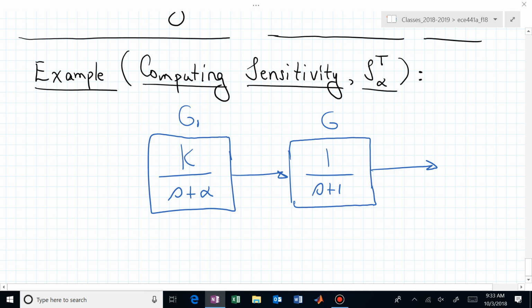It's stable, isn't it? It's in the left half plane. It would have a mode corresponding to e to the minus t. What's the time constant, open loop, of that plant or system? What's tau? What time would make that exponent be 1? Forgetting the negative sign. 1. So after 5 seconds, what's infinity? Infinity is 5 seconds in this case for the open loop.